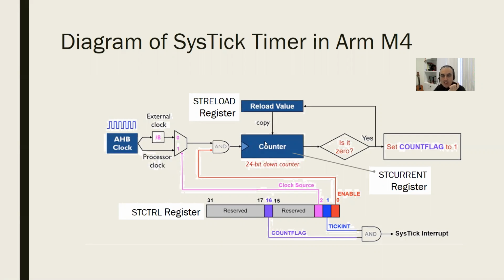The other one was connected to a counter. What was a counter? In digital design, you have seen what a counter circuitry is. A counter is, you feed a clock to it, and at each clock edge or level, depending on the type of the counter, it increments or decrements. It could be a forward counter or a backwards counter. It doesn't matter. You've done the design of a digital counter in digital design using registers and flip-flops. You know how it is.